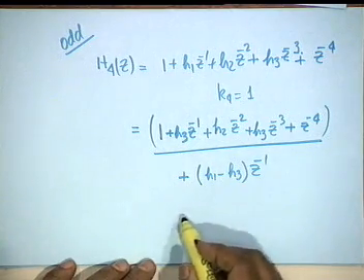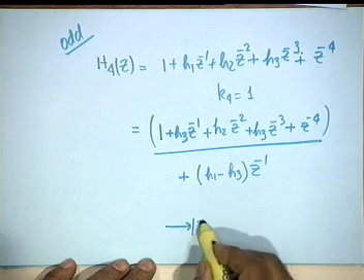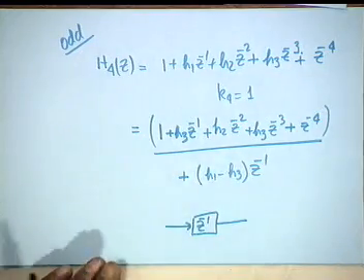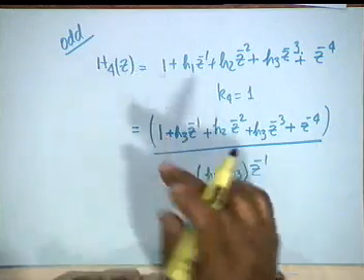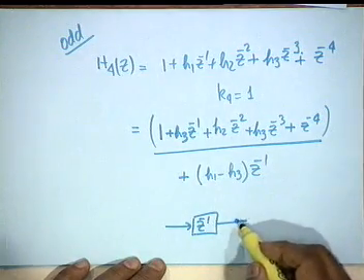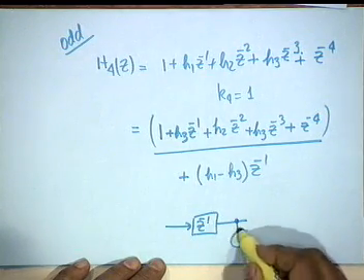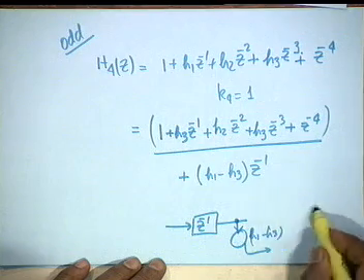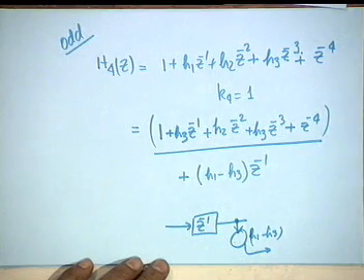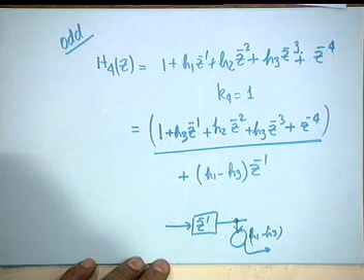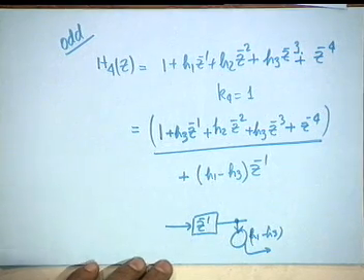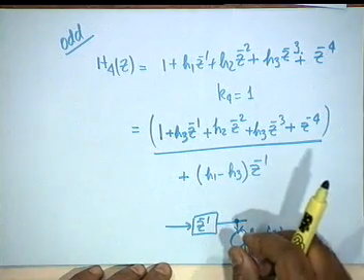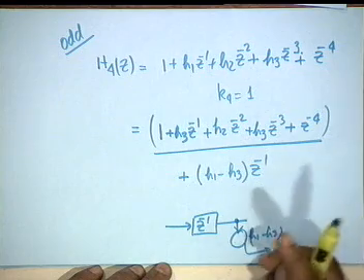That is, you have a Z inverse in the first K1 block, you have a Z inverse to start with. After this, you take a tap, multiply by h1 minus h3 and add it to the main lattice output. Okay? So that is how you take care of a general transfer function in which the last coefficient is plus 1.